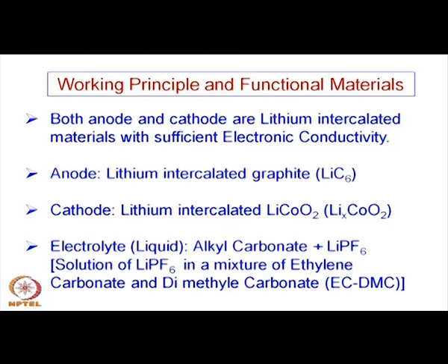Normally the layered structures have a property of intercalation. Between the layers you have a less ionic bonding, and those layers can be slightly distorted, so can be moved apart, and in between certain ionic species can come in. So, that is what is known as the intercalation, or sometimes also called insertion. These are the insertion compounds in which lithium can be intercalated or inserted into the structure of these solid materials.